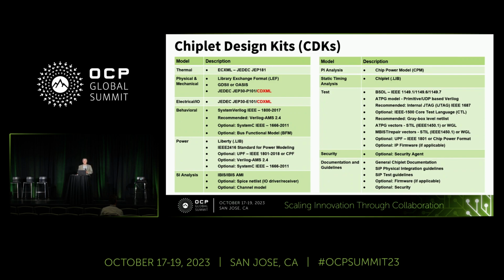I'm not going to go through this in detail, but these are the views that are necessary to integrate a chiplet into a package. You need thermal views, you need mechanical, physical views, electrical, behavioral views to support the analysis, system, signal, power integrity, et cetera. And there is some need for documentation. So most of these areas were covered.